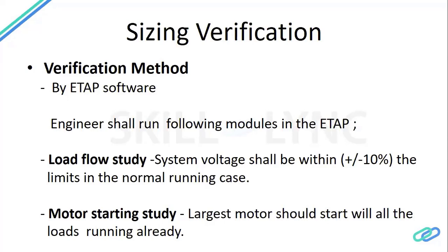So how will we do the motor starting study? In the single line diagram, all loads are running, and we will start the motor and check the voltage drop on all our switchgears and the motor. If it is within the limits, then this study is okay.